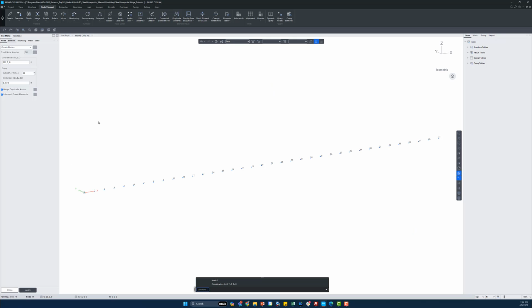So going back into Civil, I go into create element, or I can just use this particular works menu, go into the elements tab, and in here we can see the different options. For the elements tab, we'll be using create element, select the general beam, the material will be A6, so here we'll be having all the defined materials, and for the section as well, all the defined sections.